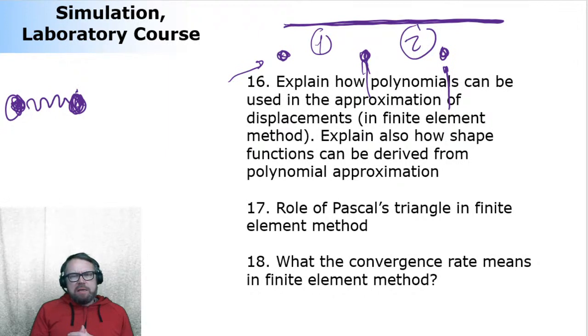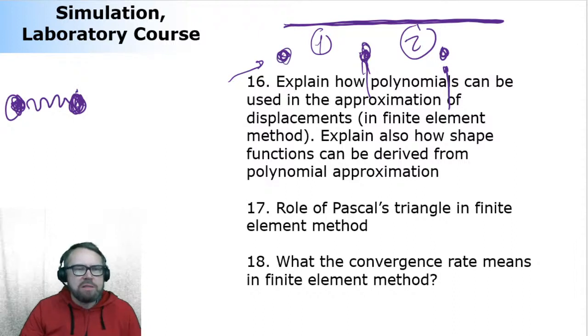It's about how we assume the particles behave between the nodes. That's what the finite element method is about. So we get started by making an assumption about how the particles behave between these nodal locations, and we describe them by using polynomials.